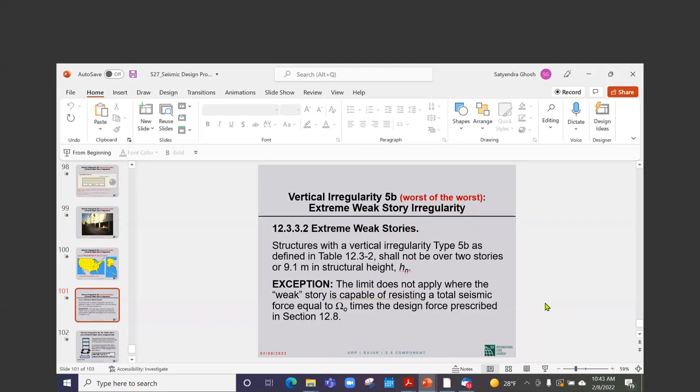If you use a rationally computed period, you are assuming a softer building, a building with less stiffness. If you ignore the limit of C sub u T sub a, you are further decreasing the stiffness of your building. If you decrease stiffness, you'll be calculating larger drifts, and the code has no problem with it.